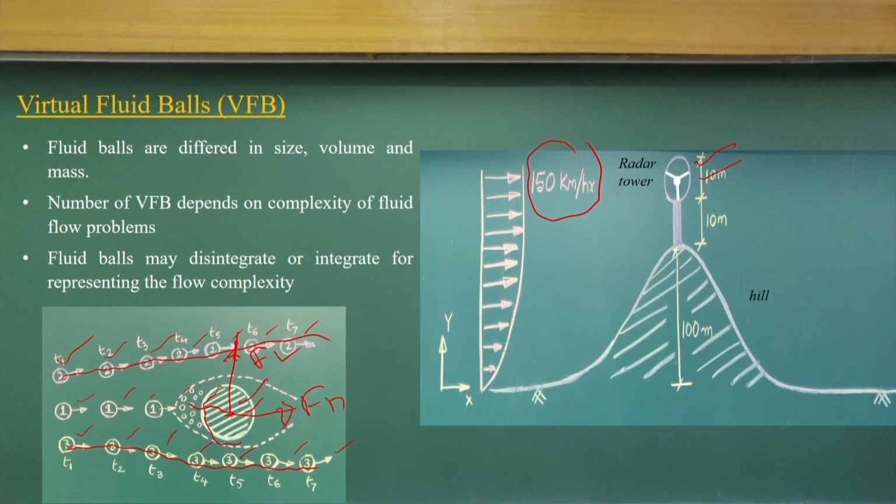As we know the velocity and pressure distribution, we can integrate the pressure distribution over this object to compute what the lift force will be and what the drag force will be. Again I tell you, it is a simplified version, but for a real field we can solve these problems either by computational fluid dynamics or by conducting a wind tunnel test. We need to do that part.